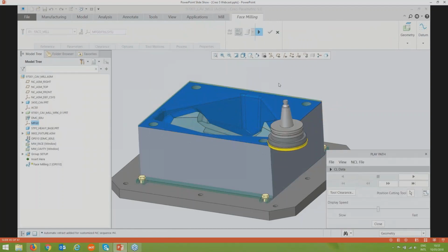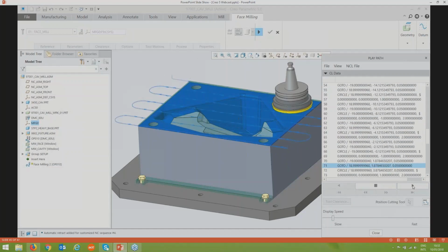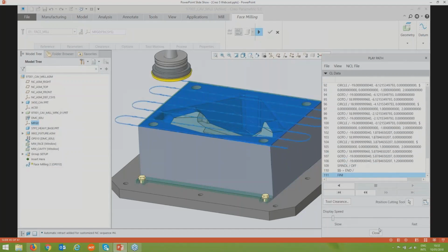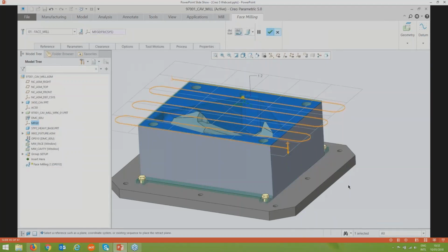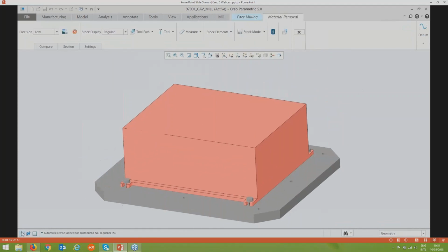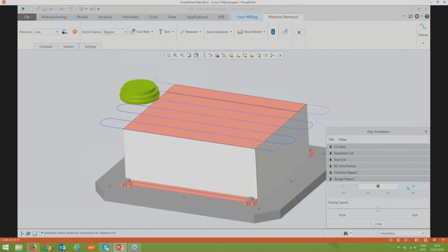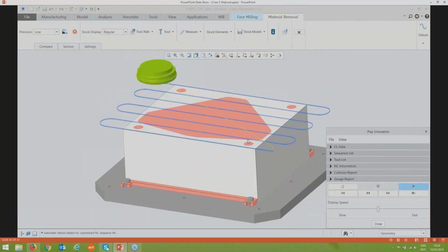Okay. Now, at any point, once you've defined a toolpath, we can come in and preview that. Okay, so we can watch that play through and check the data and make sure everything's working as it should. Or, that was just a simple play of the path. We can run a slightly more visual simulation of what's going on here. So we can bring in both the part, the tool, and the workpiece, and find out how our toolpath integrates, or we can verify what's going on here.